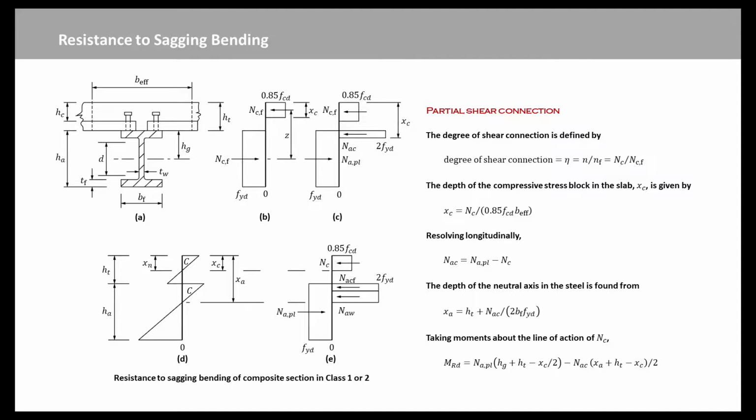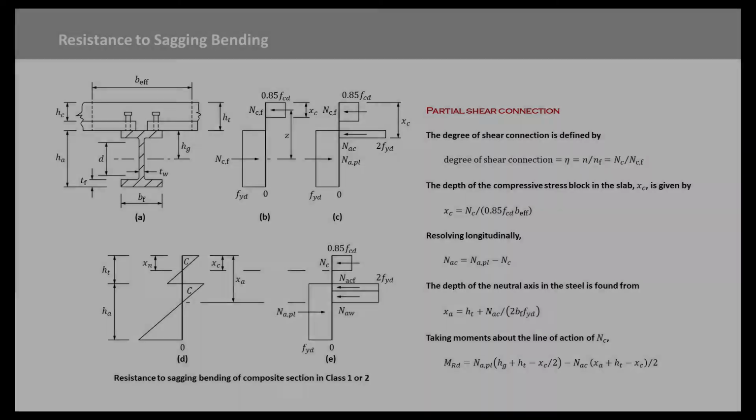A composite beam is usually designed first for ultimate limit state. Its behavior in service must then be checked. For a simply supported beam, the most critical serviceability limit state is usually excessive deflection, which can govern the design where unpropped construction is used.